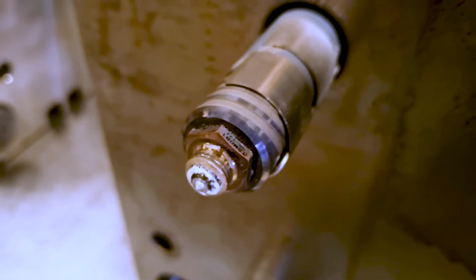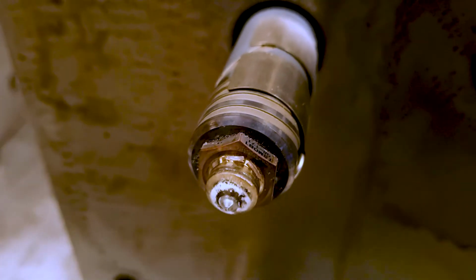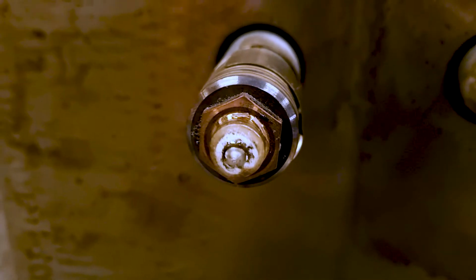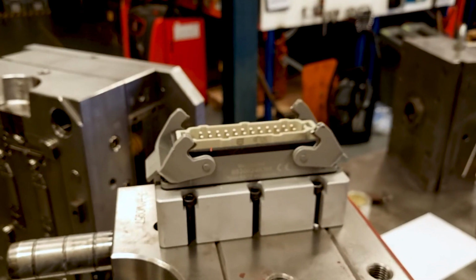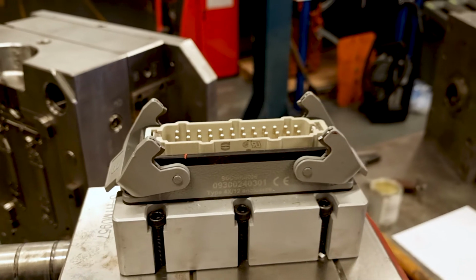The size of the hot runner channel depends on a few factors, like injection speed, polymer type, and the size of the part being produced. A temperature controller is required to heat the elements inside the runner system, which is usually controlled by the injection moulding machine.